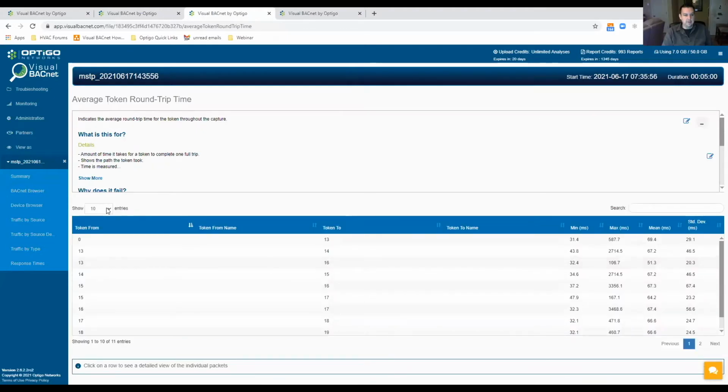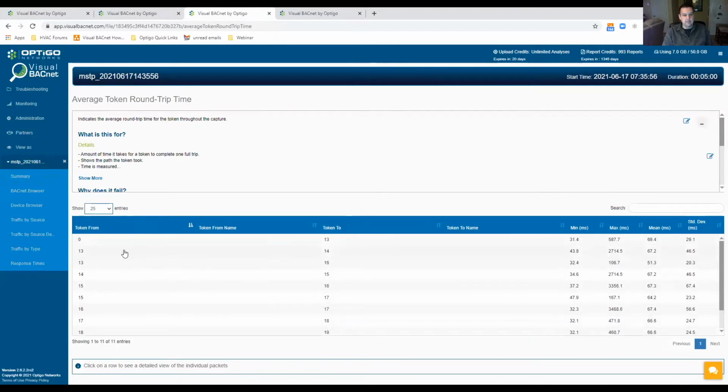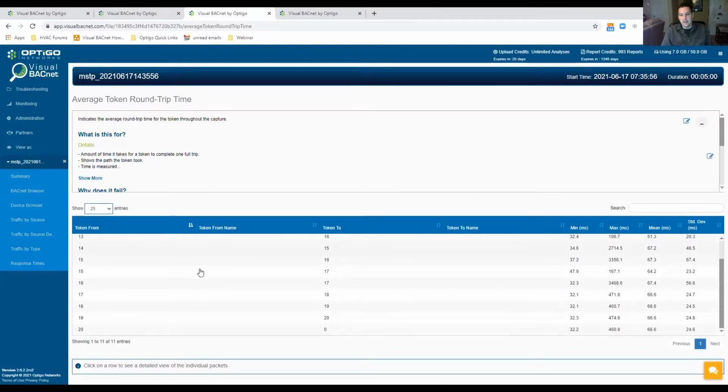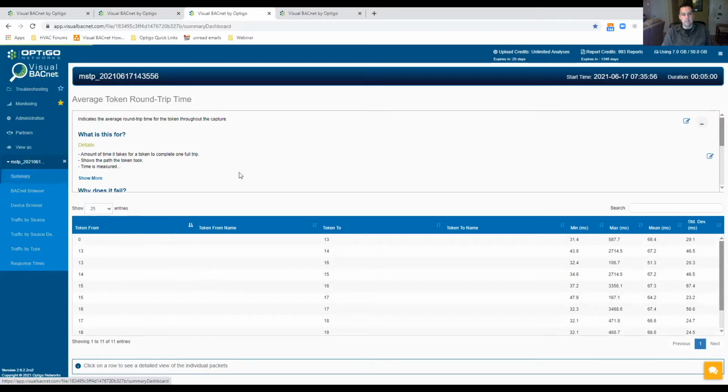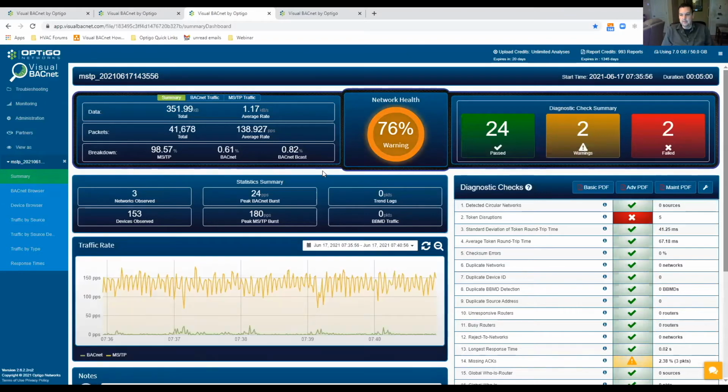Okay, interesting. And you can see here from some of your testing results that you broke the network down. Looks like you got rid of devices 1 to 12, so breaking the network in half, getting another scan. Clearly you can see here the health score went up. So headed in the right direction fairly quickly. And that process, aside from the physical labor, but sending you in the right direction, can you tell me a little bit about that? Yeah, I'd say that process and taking that approach saved us a lot of time. Once we got on top of the issues, it probably took us maybe a day or 2 days to start focusing in on where the problem was.